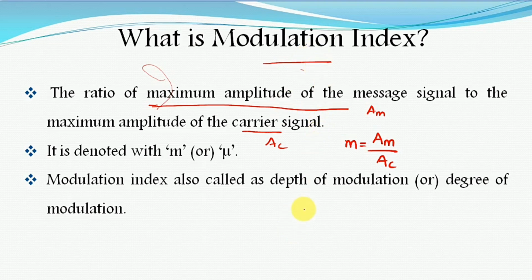For lower values of modulation index, we can definitely say that the original signal can be retrieved perfectly. For example, if m is 5 or 6, meaning the modulation index value is greater than unity, then the recovered message signal at the receiver end will be distorted, or some information loss will be present while retrieving our transmitted message signal.